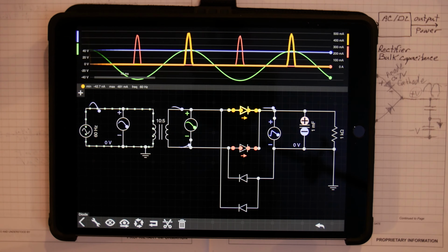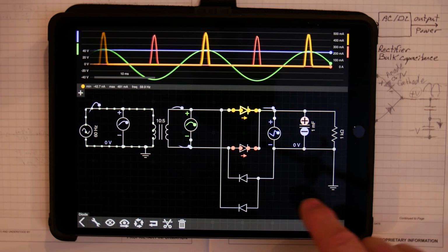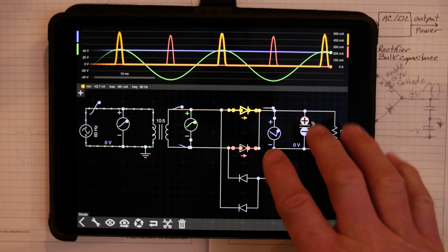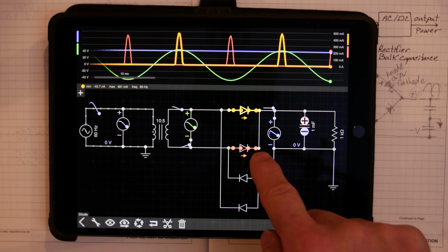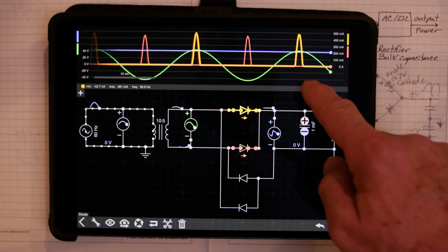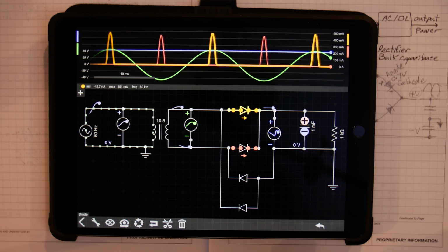So I hope that helps you understand how rectifiers work and how the diodes are used for steering the voltage, and how the voltage drops on the diodes. Even though we're getting a flatter voltage, we're getting double the pulses, we get 2 diode drops in a full bridge rectifier.